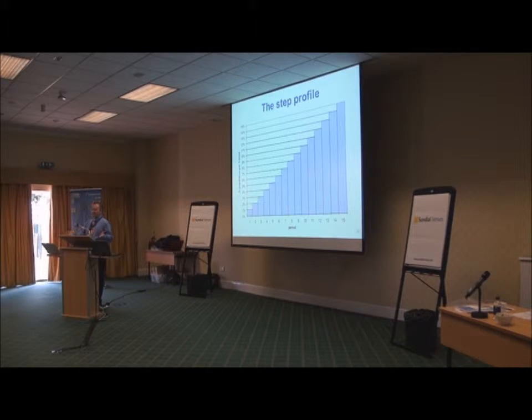So constant profiles we talked about, a really useful system test. You can use different lengths, different widths, different heights. Another really useful test I found is what I call the step profile. You call it the stepwise profile. Different people have different names, but basically it's a ramp that goes up. This one in the current version of my software goes from one step to the next step, whereas I think the Otis one and the Kone one has a step, then stops, and the next step, and then stops. So there are different ways of doing it. But anyway, this is my one for what it's worth, and I found it really useful.